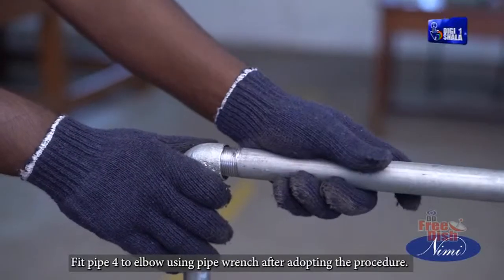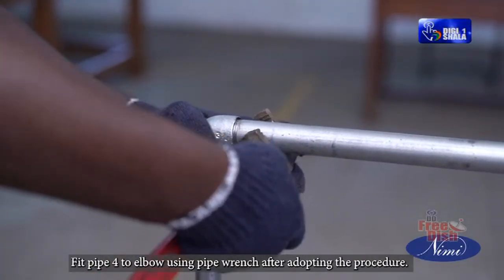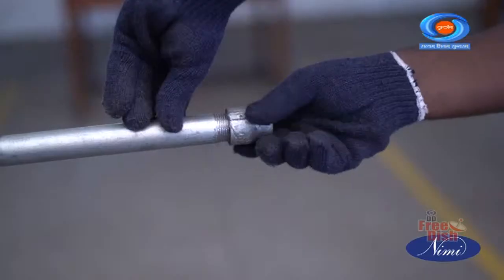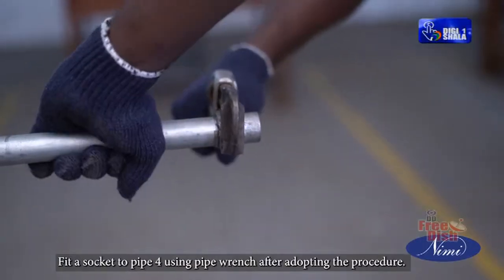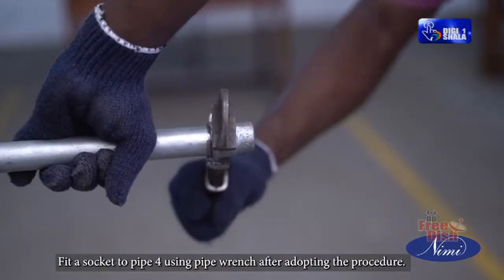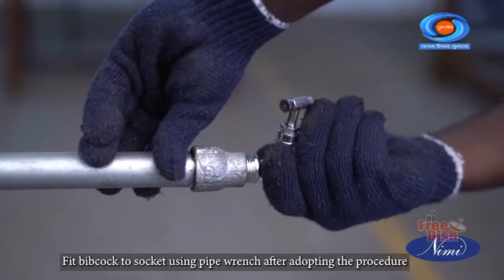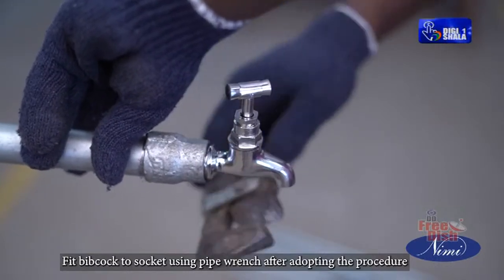Fit pipe 4 to elbow using a pipe wrench after adopting the procedure. Fit a socket to pipe 4 using a pipe wrench after adopting the procedure. Fit bib cock to socket using a pipe wrench after adopting the procedure.